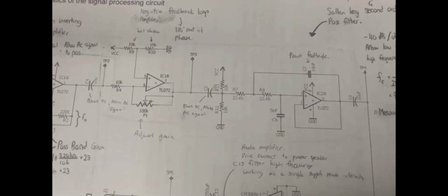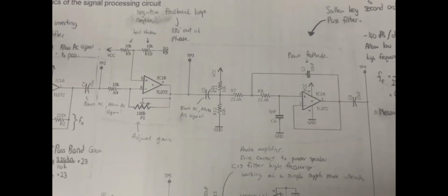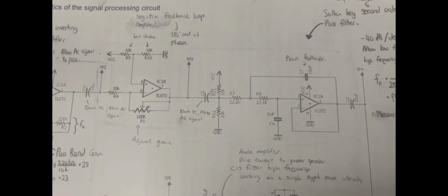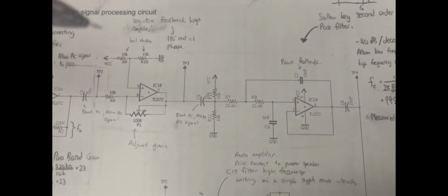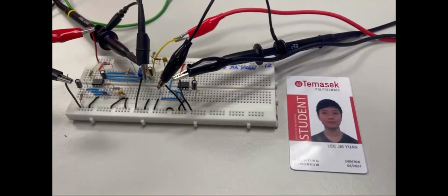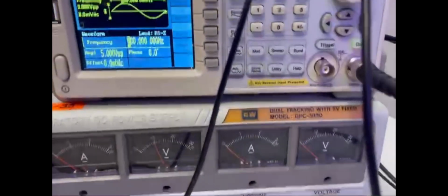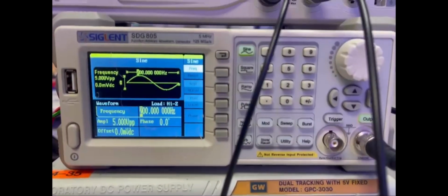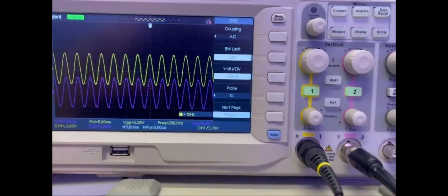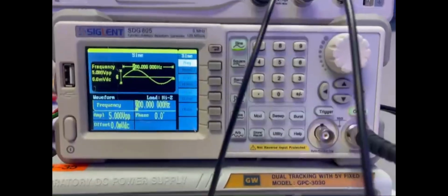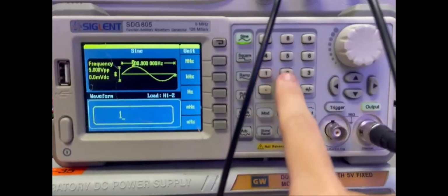The steps are the same as measuring TP2 and TP3: we connect the oscilloscope and function generator to TP3 and our other oscilloscope probe to TP4 to test the output. For TP4, at 200 Hz, 5 V peak to peak, our voltage is 5.12 volts. But at 1 kHz, 5 V peak to peak, my voltage is 3.04 volts.